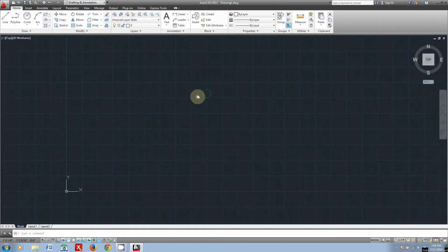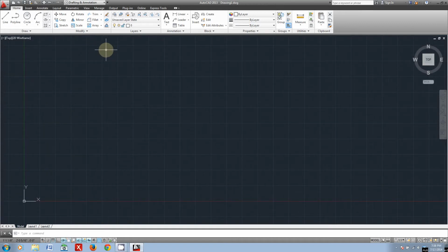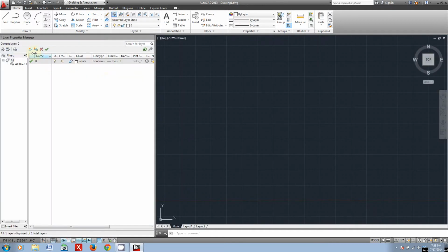Now, let's next take a look at some of the other options for creating layers. Now, obviously, if you're going to be using this file for generating a bunch of design files, you want to have a lot of preset dimensions and other things like layers, just to specify that, okay, this is going to be a decking support surface, or this is going to be a webbing or something like that. So it can be very useful to have preset layers that you can import into SAP later, and the more descriptive of the name, the better.